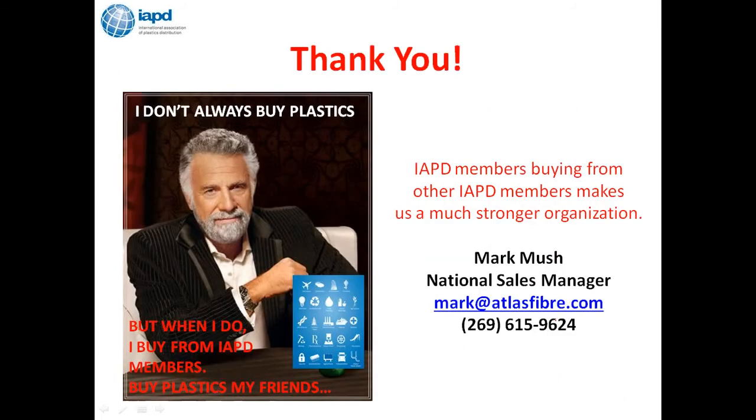And then they have delaminate in parentheses. Delaminate. I think that it'll certainly degrade faster than it's just out in the general atmosphere. Let's say for paper-based, canvas, and linen, the phenolic grades, I would say, would be affected more quickly than any of the other grades. However, the term used was water, but if you expanded that to other fluids such as transformer oil, it turns out that the paper-based grade is a terrific insulator within oil-based transformers. So it depends on the fluid that you're talking about.